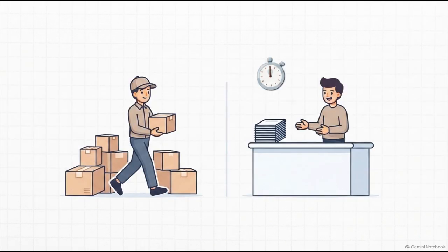But the 8086 speeds this whole cycle up with something brilliant, an instruction queue. Instead of the chef just standing around waiting for the delivery person to fetch the next recipe, the BIU can fetch up to 6 bytes of instructions in advance. It creates a waiting line. This means the chef always has the next order ready to go. Such a simple queue, but it was an absolute time saver for this architecture.